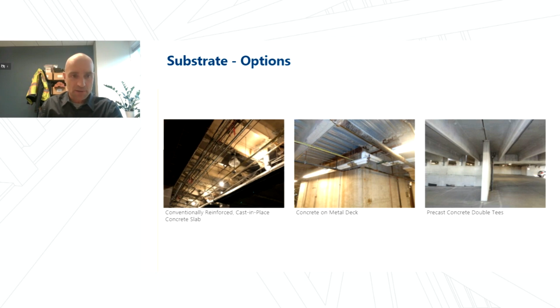With precast structures, they've typically got a concrete topping slab to cover their connections and to cover the offsets between adjacent planks. The topping slab is prone to crack along these joints. More importantly, an item to keep an eye on: rotation of the precast concrete members at the support end can cause the end joints to open and close. And when we detail slab to wall transitions, we need to pay close attention to this type of movement. We might want to consider detailing some of these joints as if they're expansion joints.